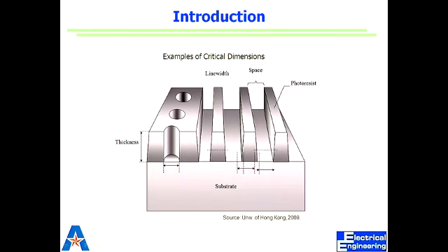So what would be the critical dimensions we'd be worried about? Thickness of resist, diameters of holes, widths of lines, spacing between lines, and for any feature, the angle of the exposed feature. All these things, or some of these things, or maybe one of those things will define a critical dimension. Right? So when I'm done with my exposure and development, what do I look for? First thing, I want to go look for CD. That has registered accurately or not.